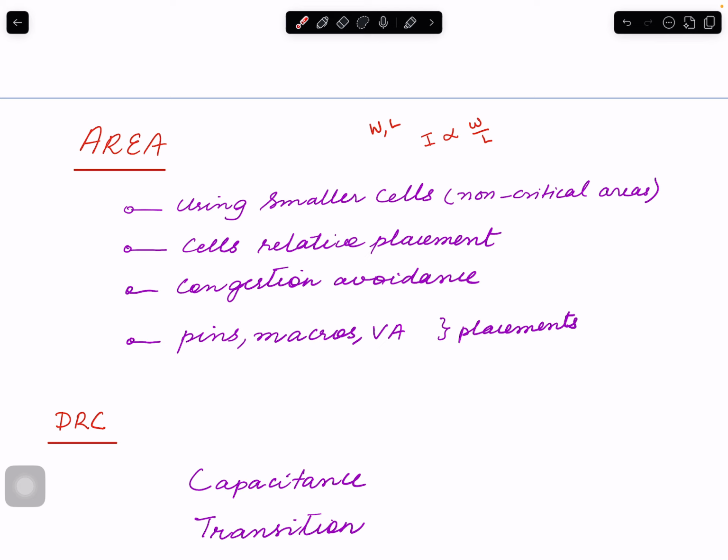Okay, so a lot of things to talk about, but the bottom line is area is an important consideration during synthesis, and the tool is going to do a lot of optimizations that it can do. It depends on what your highest requirement is. Is it timing? Do you want to meet timing at the expense of area? Is that good or not? Or is area your biggest concern and you can reduce the frequency?